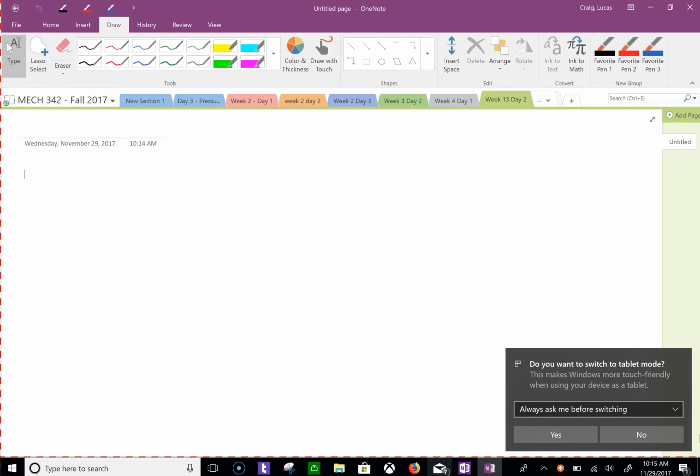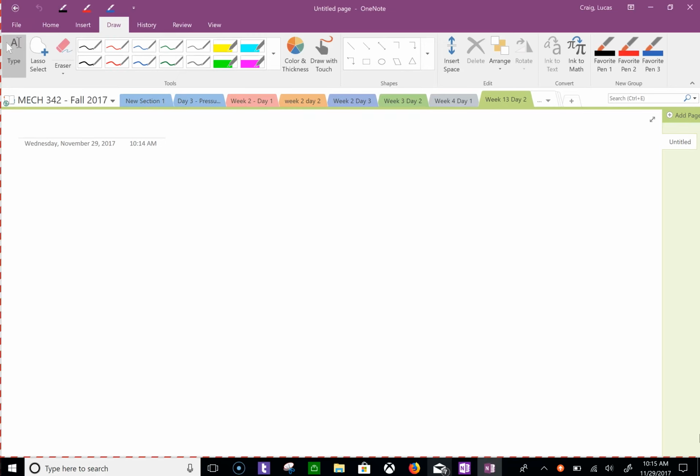So considering a Carnot heat engine cycle executed in a closed system using 0.025 kilograms of steam as the working fluid, it is known that the maximum absolute temperature in the cycle is twice the minimum absolute temperature, and the net work output is 60 kilojoules. If the steam changes from saturated vapor to saturated liquid during the heat rejection, determine the temperature of the steam during the heat rejection process.